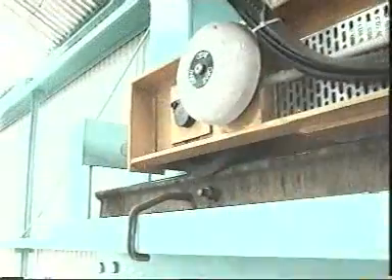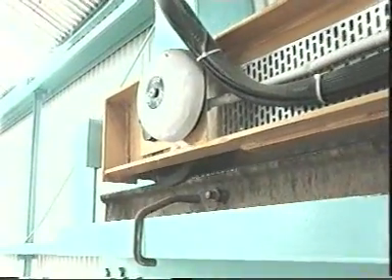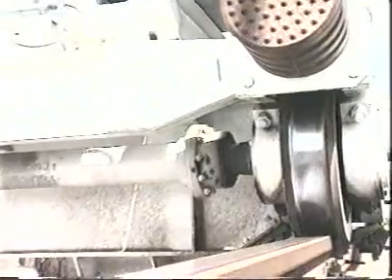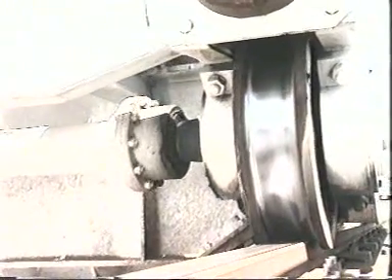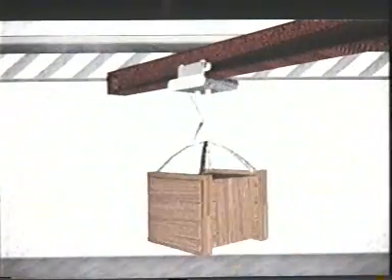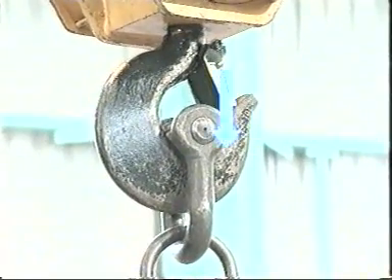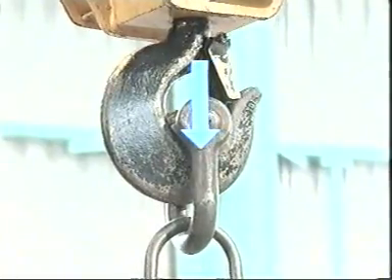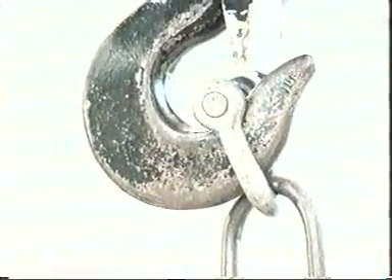When engaging the crane with end stops, do so gently. Continuous impact may cause the stops to weaken and eventually fail, possibly causing the crane to derail. Always lift the load using the center of the hook, where it's designed to take the weight of the load. Lifting the load off-center can stretch the hook.